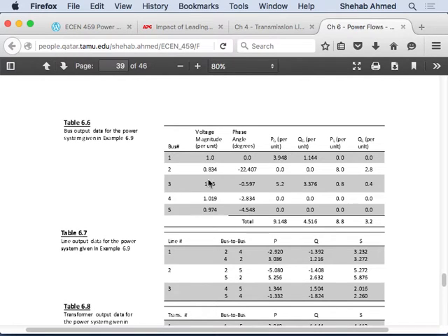At the other buses, the angles did not change significantly from 0, because there are no real power loads at these buses, okay? So it seems like real power and angle are more correlated, right? And then look at the voltage of the other buses. Did they change much? The voltage of the other buses are all closer to 1 per unit versus the voltage at bus 2.